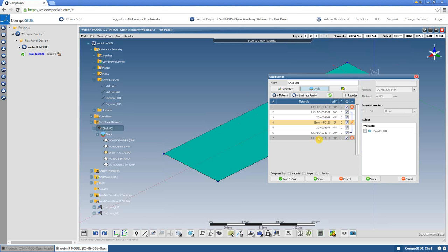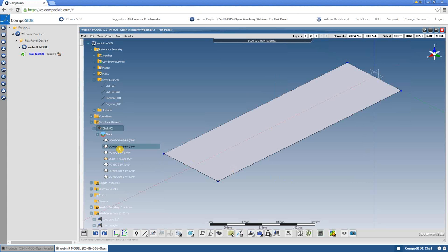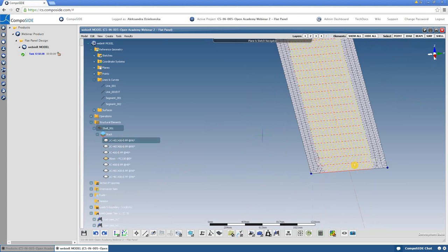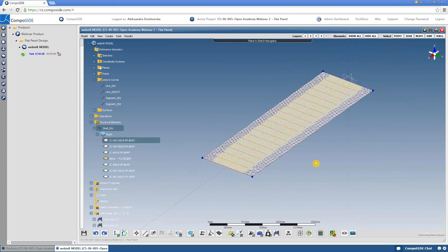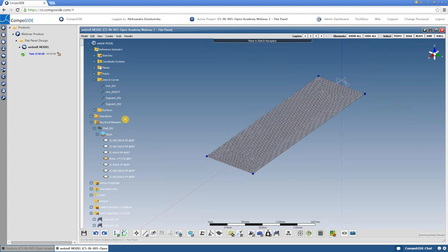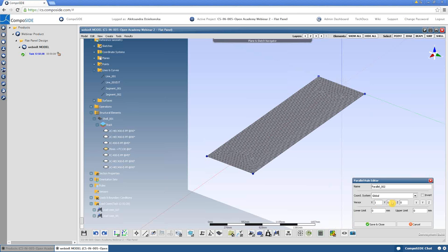Let's also add the rule. As you can see, Ola has allocated to those 2 local plies the rule, which is basically showing the local ply. The extent of the rule basically drives your ply extent, and you can do multiple rules. Maybe Ola will add another rule, which is basically limiting our extent of a ply in another direction. So you can think about different rules that can be applied.